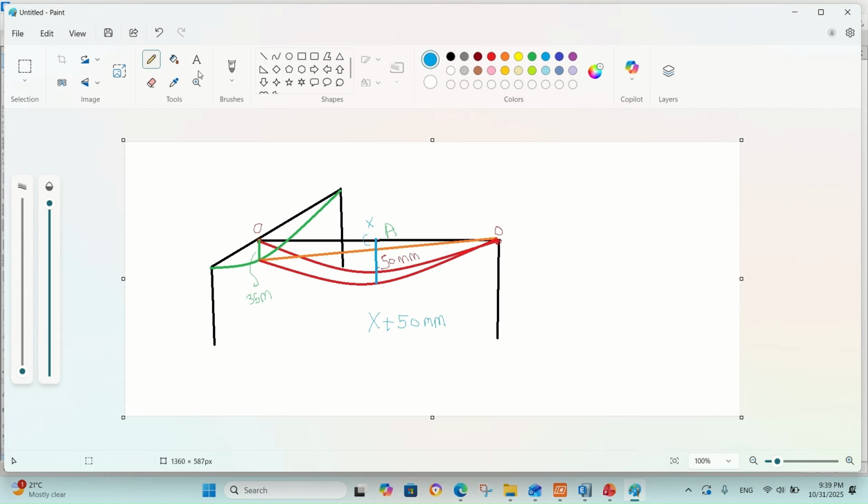So number 3 will be somewhere here, because here also, due to the rotation of the joint, it will have a value of deflection in the Z. And if this beam in its turn is supported on another beam, all the deflection values will be seen at the absolute.